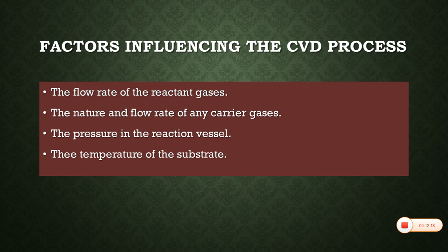Good properties include thermal stability at the vaporization temperature and sufficient vapor pressure at a reasonable temperature, so they can be effectively used for gas phase delivery and for the growth. The molecules must be obtainable at high purity and must not undergo any side reaction which would lead to contamination or degradation of the film.